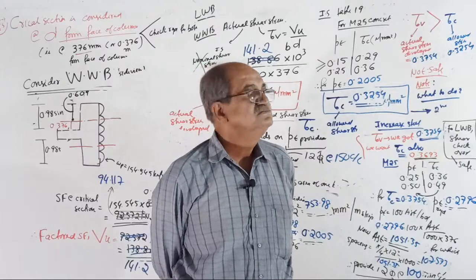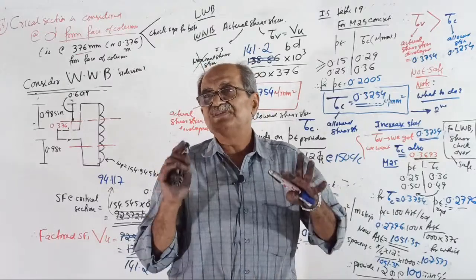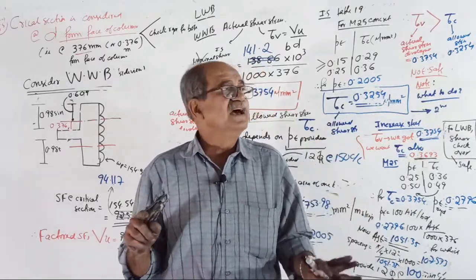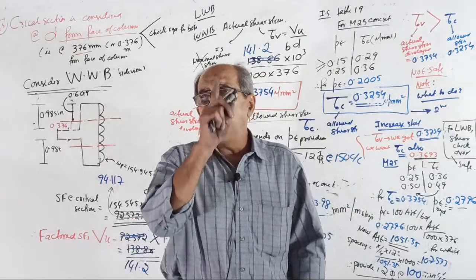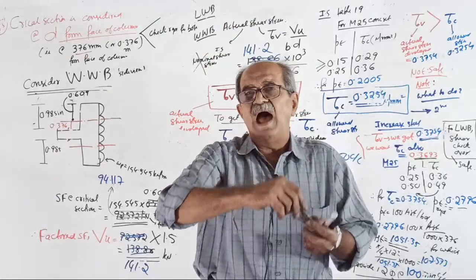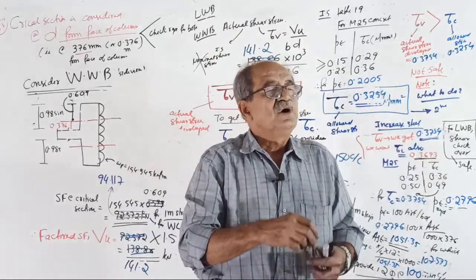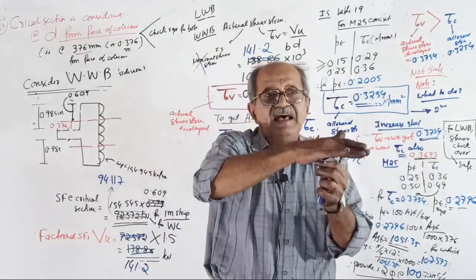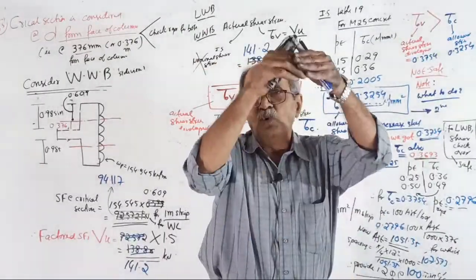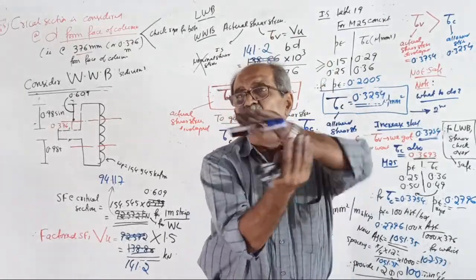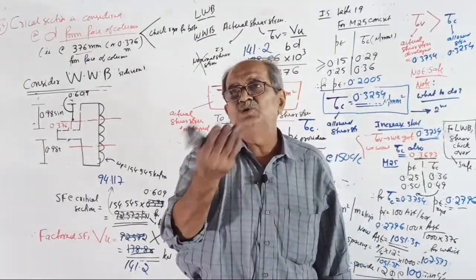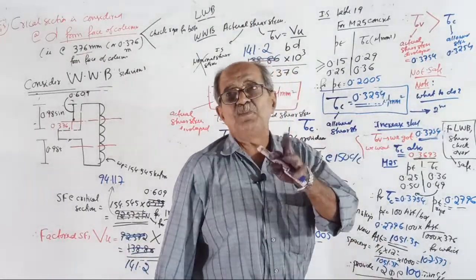You don't believe them. When you are in the serious structural design field, every column and every footing you design, the column will be subjected to axial load with biaxial bending, and the footing also, axial load with biaxial bending. So P, M1, M2 will come. That is our next question.